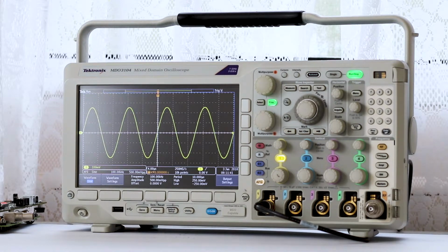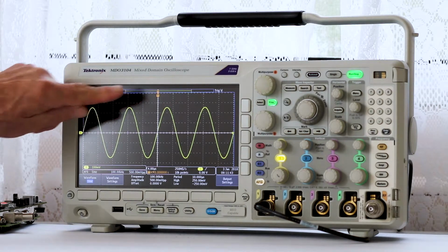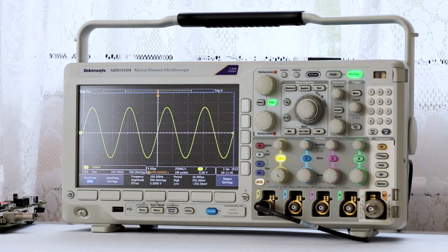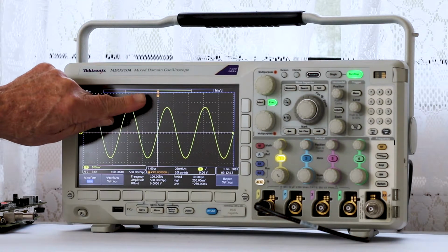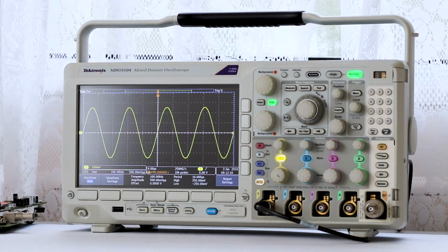Trigger point is denoted on the screen by an orange T. Horizontal position is the time from the trigger point to the expansion point, when delay mode is on. It can be adjusted by turning the horizontal position knob. Use a positive time to acquire the record after the trigger point, and use a negative time to acquire it before the trigger point. Expansion point is denoted by an orange triangle. It is the point that the horizontal scale expands and contracts around.